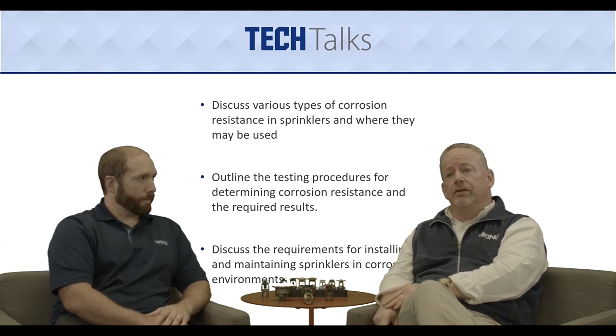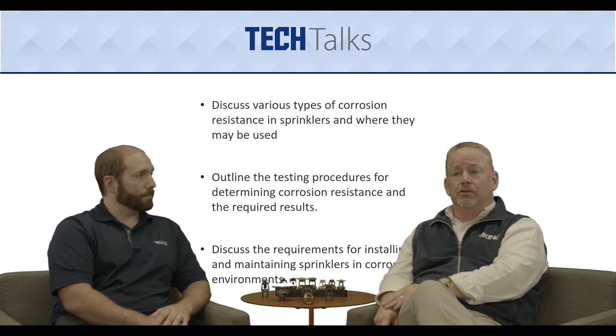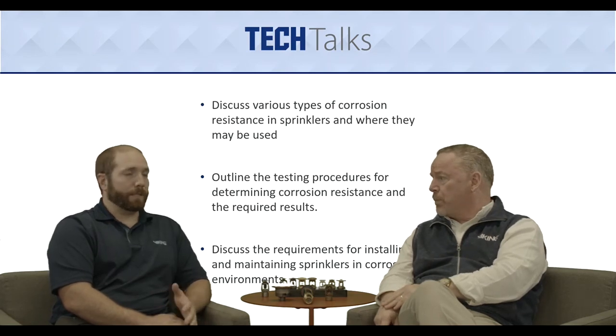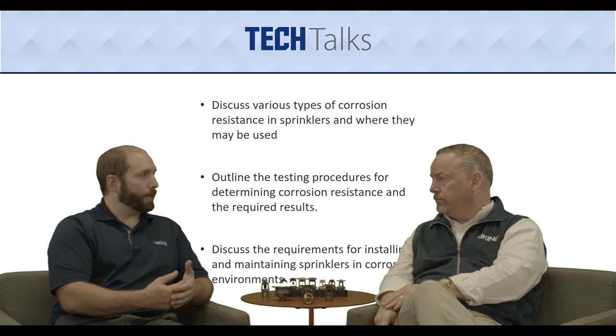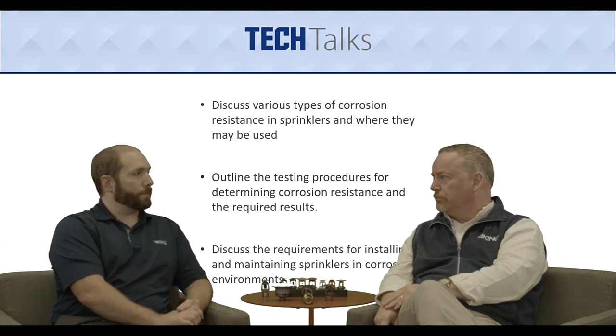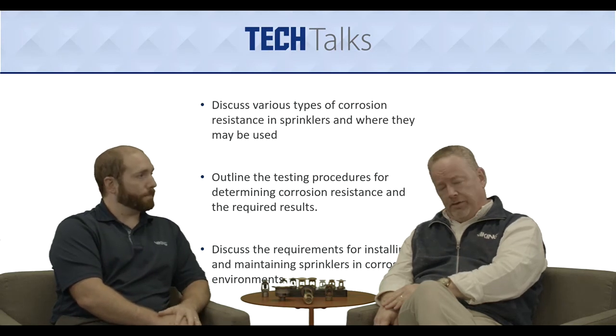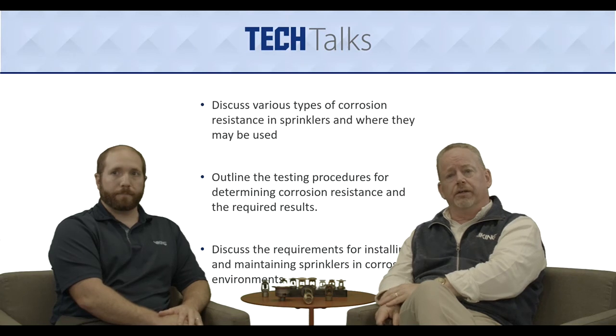What about a room with water softening equipment in it? Lots of salt, I'm guessing, in the dust, kind of commercial grade. What about that? I would suggest an ENT finish for that salty air. It has anti-adhesion properties, it has a hard resistant coating, and it's going to fully coat that sprinkler. So ENT for salt air, for the water treatment facilities, that water softening.